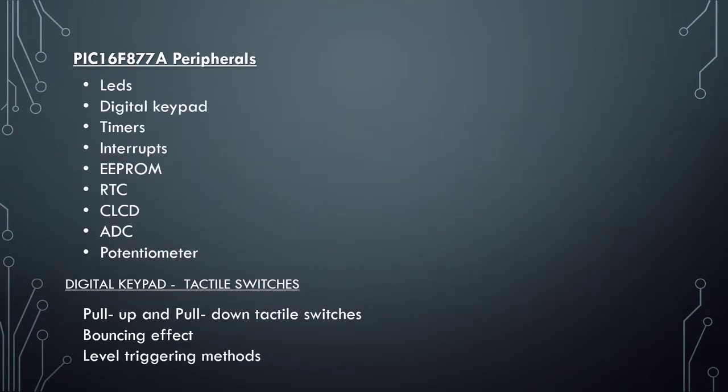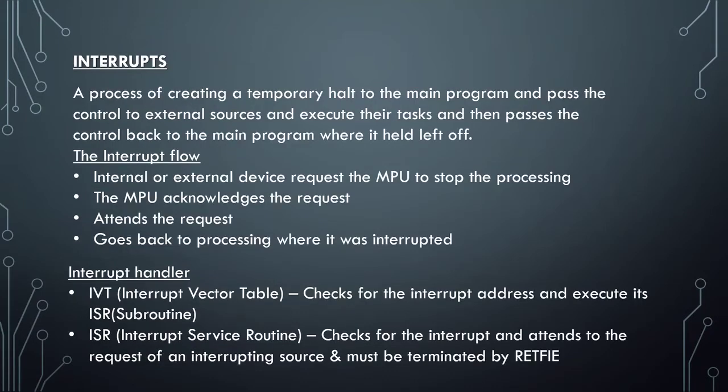So what are some of the peripherals attached to the microcontroller? We have the LEDs, the digital keypad, the timers, the interrupts, the EEPROM, the RTC, which stands for real-time clock, the CLCD, which stands for character liquid crystal display, the ADC, the analog to digital converter, and also the potentiometer. In the internship program, we looked at the digital keypad, specifically the tactile switches, where we had the pull up and the pull down tactile switches. We also looked into the bouncing effect of the tactile switches, and the level triggering methods used with them.